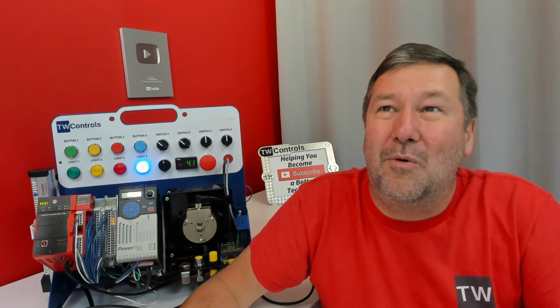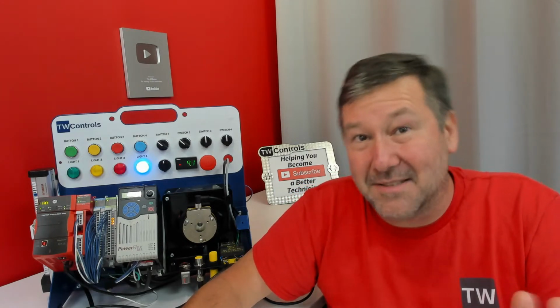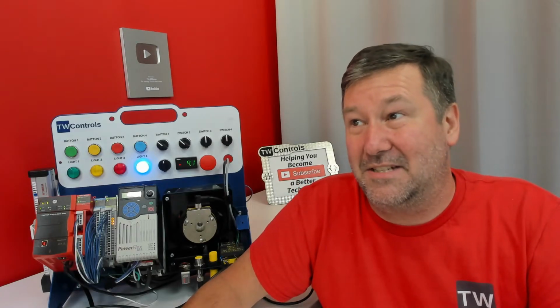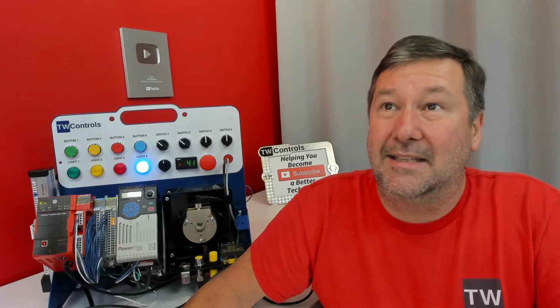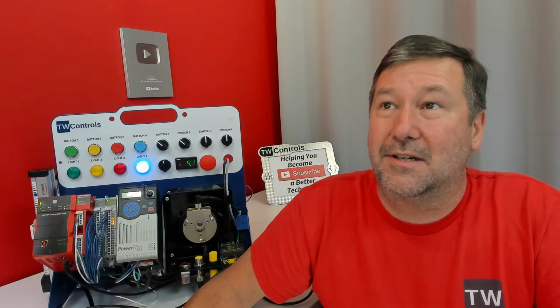Now, let me talk you through one other issue that you will run into. Sometimes if we plug into a plant, there will be a DHCP server. But just because you get assigned an IP address does not mean that you're going to be able to communicate with your PLC. So now I'm going to enable a DHCP server on mine, and then we will plug into that network.